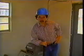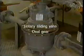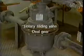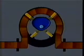Now that we've seen the basic components of the positive displacement meter, let's look at two meters, the rotary sliding vane and the oval gear. The rotary sliding vane meter consists of a single or double case housing, a cylindrical rotor which revolves on a ball bearing around a central shaft, and a stationary cam. The rotor has 4 or 6 evenly spaced slots which provide guides for the blades.